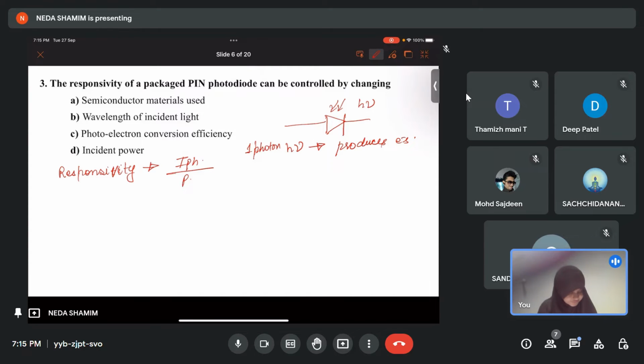So this one photon is producing some electron flux, a few electrons per second. Every photon is producing that electron flux, say phi, and so how much will my photocurrent be? Photocurrent I_P will be equal to e times the electron flux. Here phi is the electron flux, that is the number of electrons per second. If the number of electrons per second is phi, how much current will be produced? That times the electronic charge. That much photocurrent will be produced per photon.